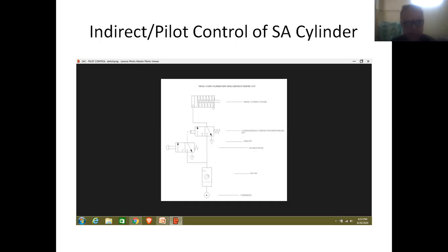So friends, in any case, the push button is used for putting the valve in first position, and the return spring is used for putting the valve in second position. As usual, the first position of the pilot valve is used for performing the forward stroke of the piston, and the second position of the valve is used for performing the return stroke of the piston.